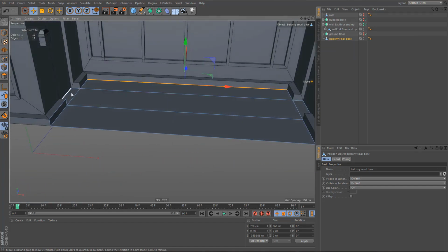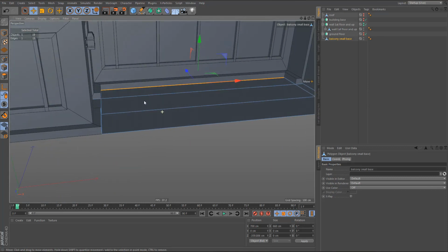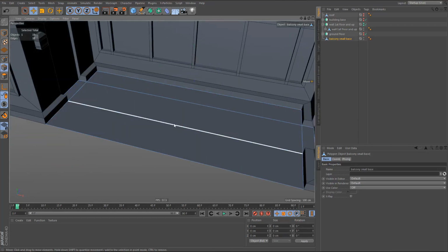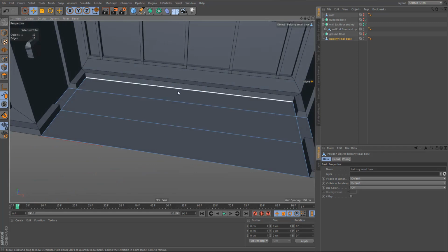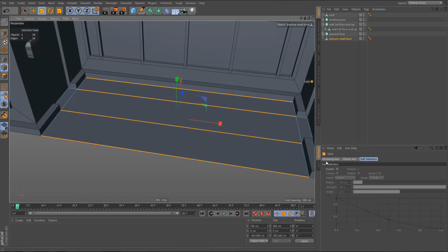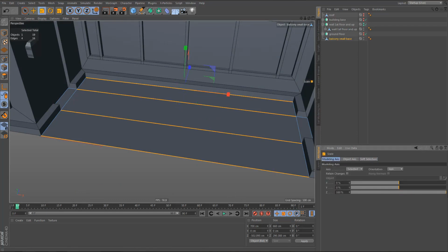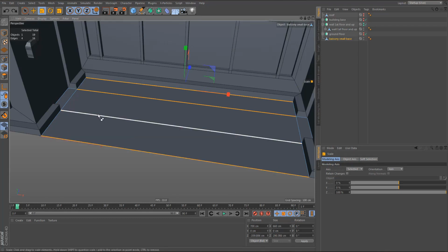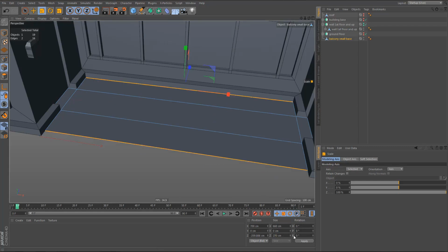So we've made this flush with the doors and the bottom of this area here. Let's delete this edge. And let's see, I'll just select these edges here, and these have a depth of 290. I'm going to change that to maybe 270. Let's undo that, deselect these edges here. I just want to scale the edge at the back and the one at the front. So 270.